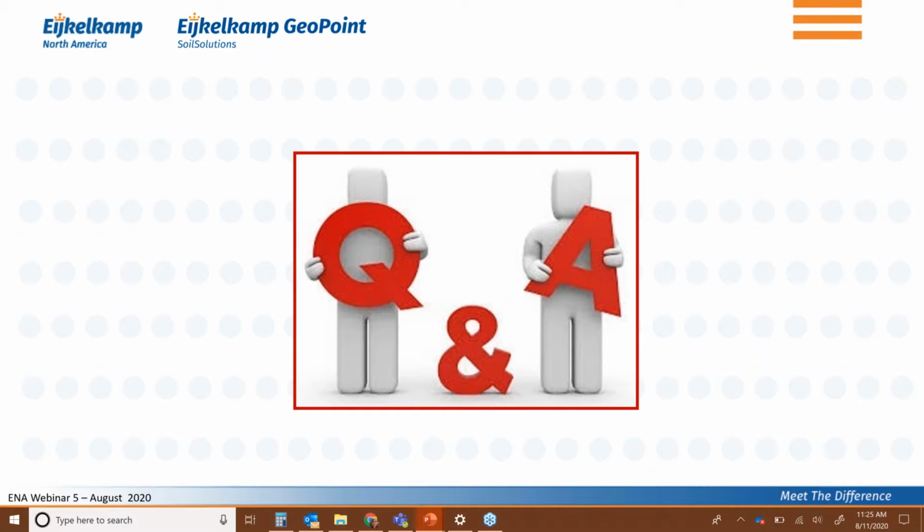Excellent. Gerald, I've got a couple questions for you that just came in. One is, what about inclination adjustment? Do you just use the drill rig itself, or how does that happen? Yeah, basically what will happen is you level your drill rig, and once that is leveled, you make sure that the unit, since the Drill'n CPT is firmly attached through the clamps to your drill rig, is sitting vertically, and there's a check in there that it is indeed vertical.